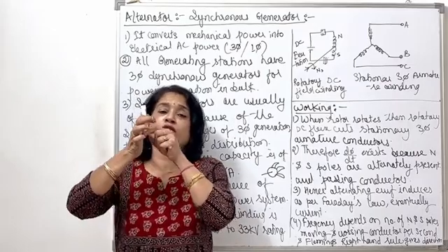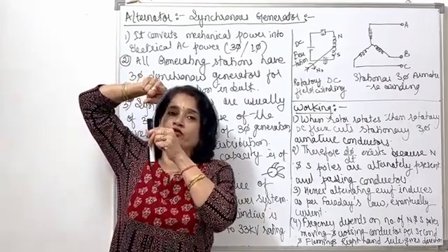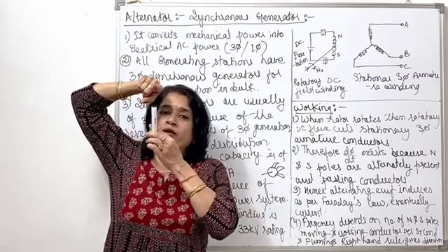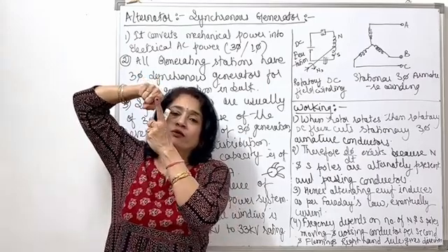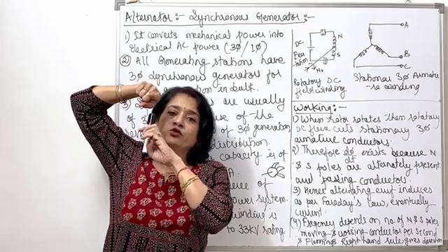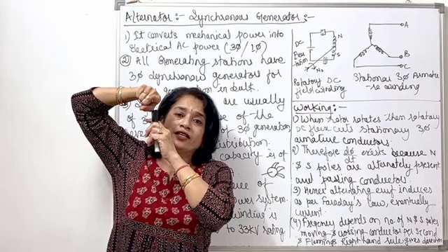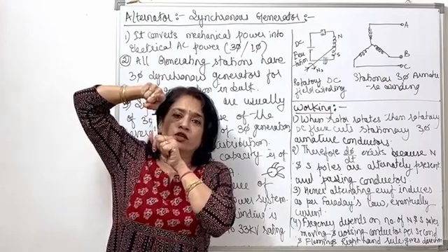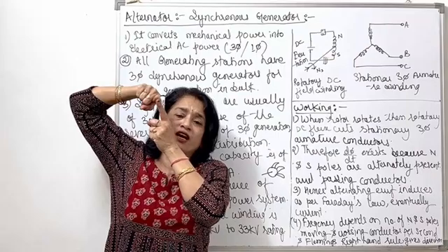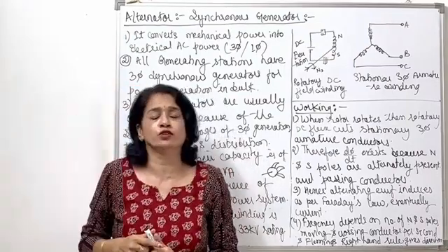Why AC? Because a conductor is first under the impact of the north pole, later under the impact of the south pole. If this conductor has plus polarity of EMF due to the north pole and negative at its back end, then as soon as the south pole comes over here, this terminal would have negative polarity and the back end would have positive polarity.